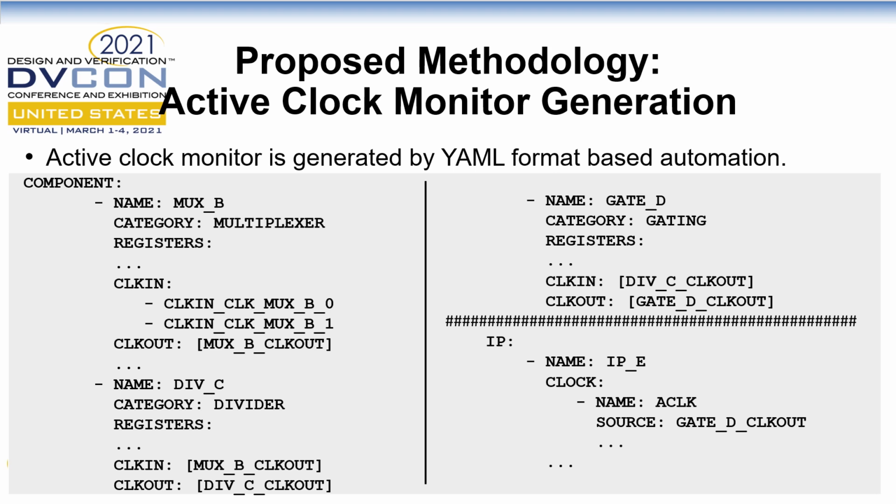If there is a mux in the middle, the total number of cases where the IP clock can be controlled will increase according to the input count of the mux. Even in this case, the ACM should know about all CMU components related to the IP clock.